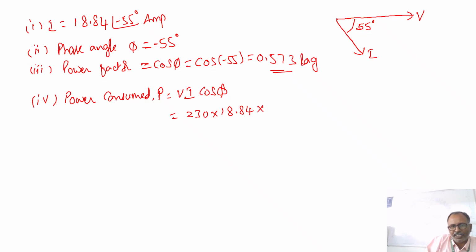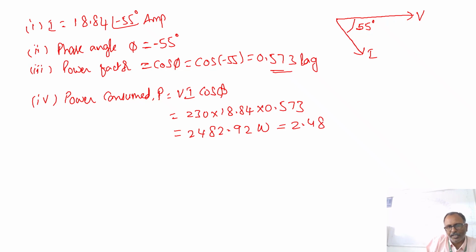We need not take the angle, only magnitude is sufficient. And power factor is 0.573. So when you multiply all this, you will get 2482.92 watts, which is approximately 2.48 kilowatts.